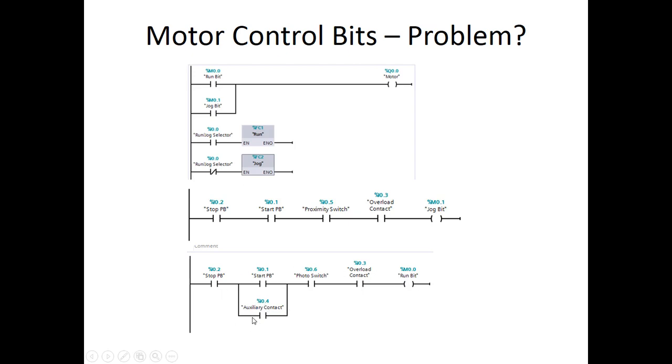But that's why it was important to have that auxiliary contact here, because that likely was going to drop this circuit out as soon as we rescheduled the run. If we were in the jog and it was off jogging, when it comes back into here, the aux is immediately open, and even though it might have thought this was retentive, when we jumped out, it immediately would deactivate.